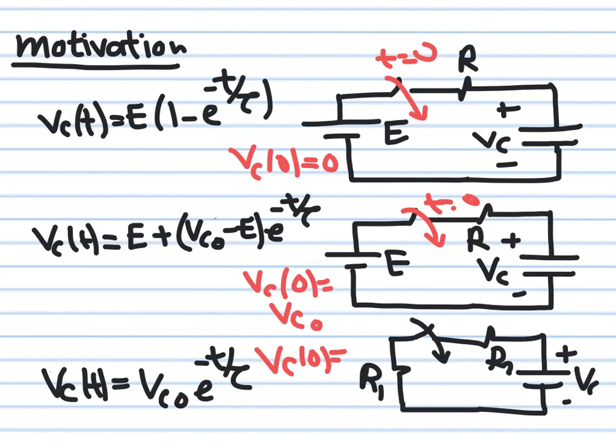So this allows us to put a general template for any circuit containing a single energy storing element, like a capacitor or inductor. So let's see this form, and then once we have this form, we'll try to find its coefficients by imposing initial conditions, by imposing steady state conditions, and by finding Thevenin equivalent looking from the side of that energy storing element.